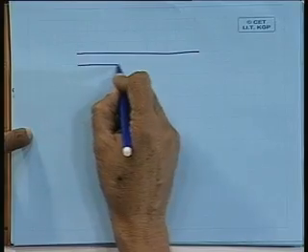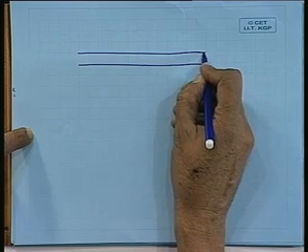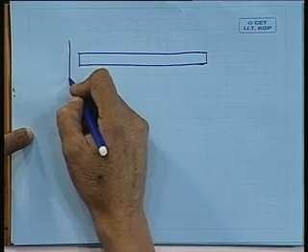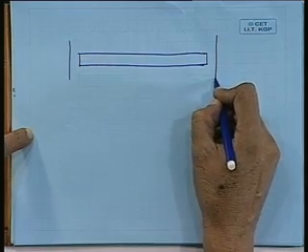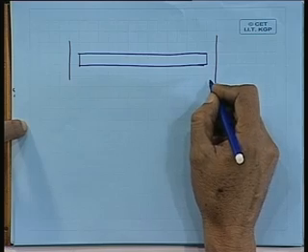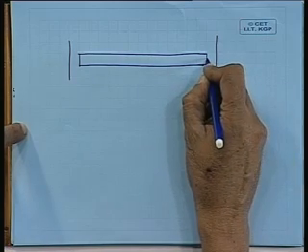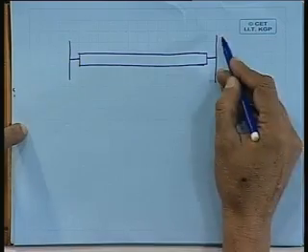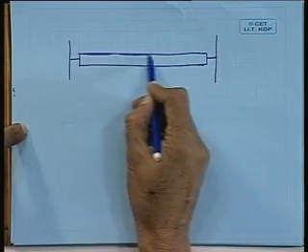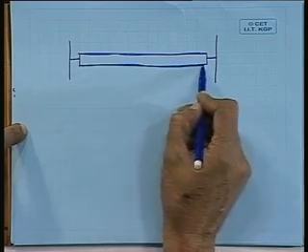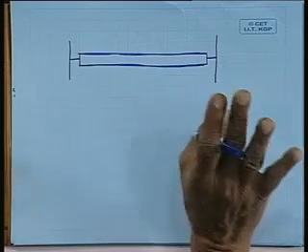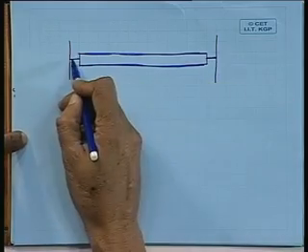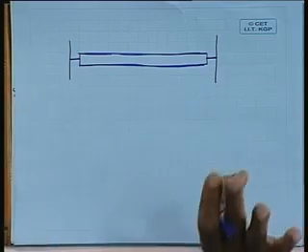is, suppose you take a bulkhead like this. I don't know whether it has been implemented or not, but people are in the thinking stage, and I am also thinking for the last 5 years, but I am not in a position to do any substantial work on it. Say you have the side shell, and you take the bulkhead, which is a double plated structure, and how you connect it in between is a different thing altogether. Now the basic idea is that this bulkhead will be connected by small strips wherever welding is required.